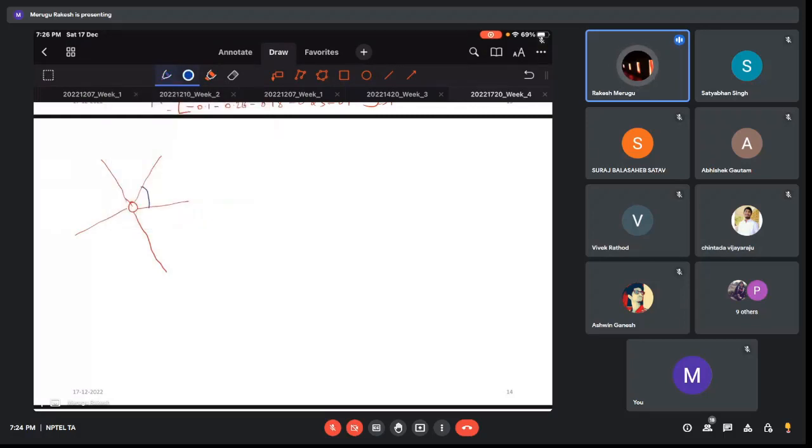I have the angle for this, that is 60 plus or minus 0.1, 112 plus or minus 0.3, 135 plus or minus 0.5. This is 30 plus or minus 0.4. Now you have to find what this value is as well as the tolerance.